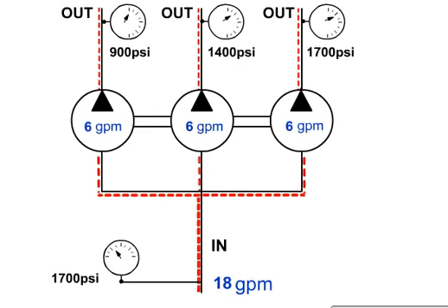The gear-type proportional divider can divide the flow into two or more flow paths. The positive displacement of the gear sections produces a constant division of the flow, even if the loads and pressures in the output circuits vary. The output flows are proportional to the input. As the input varies, the output flows will vary proportionally. If one of the output flows becomes blocked, all of the output flows will be blocked.